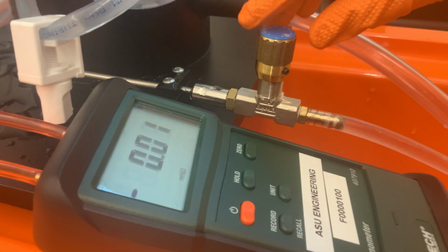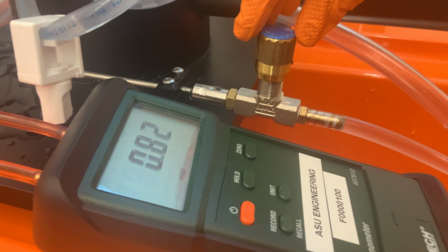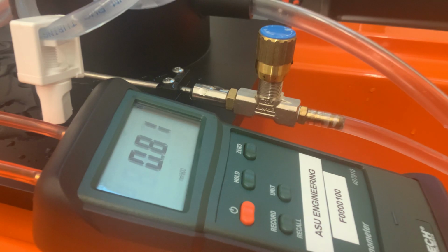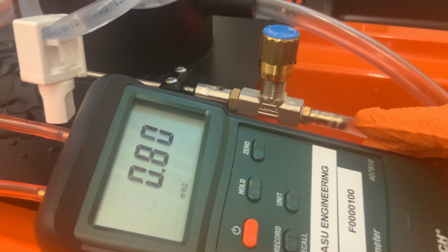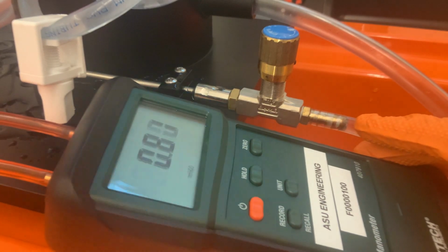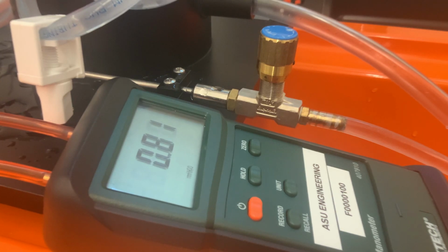Now I'm going to open the valve, and water is flowing. I think you saw the bubble going through. So now I can take the head loss. The difference is now showing us the head loss between the top part and the bottom part. So the reading is 0.8. If you see the unit, I put the unit as water meter. So it is 0.8 meter head loss.